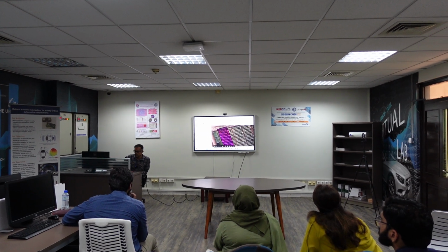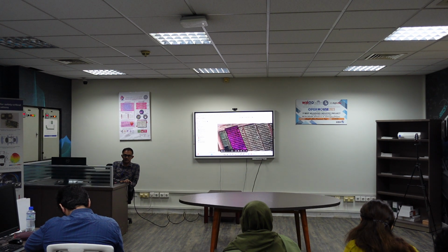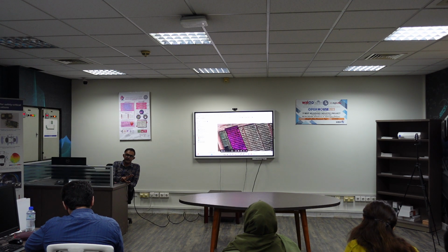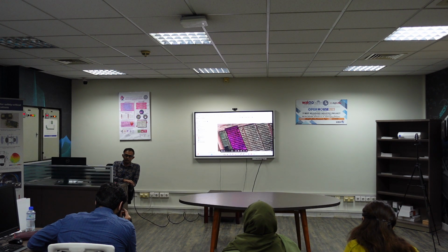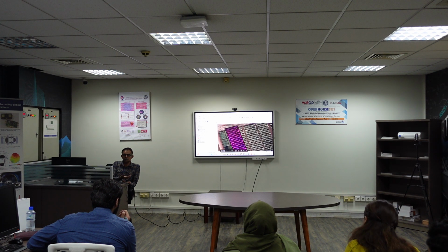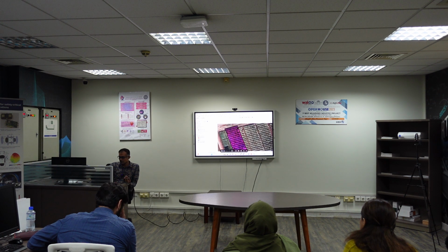Before moving forward, there is one more thing we can do. You may have heard the term vegetation indices. Vegetation indices are simply the arithmetic manipulation, or arithmetic combination, of these multispectral bands. So what we have seen so far is that NIR is very bright for the vegetative part, whereas red is quite dark for the vegetative part. How can we use this information to our advantage? We can combine both and increase the contrast.